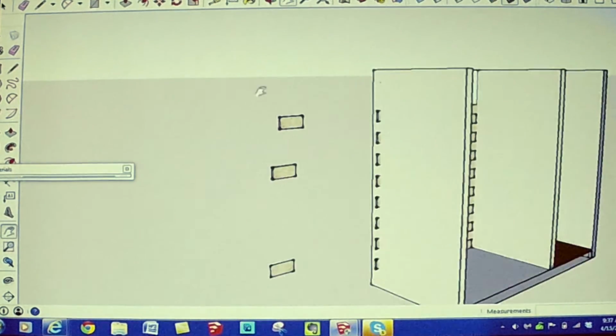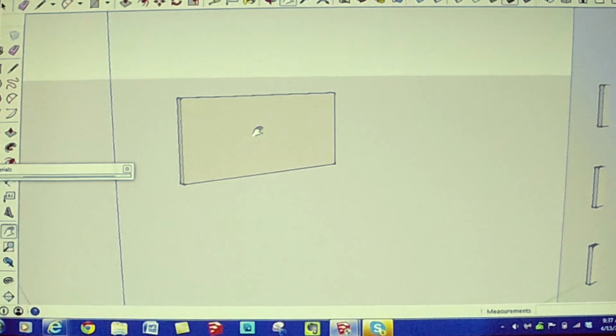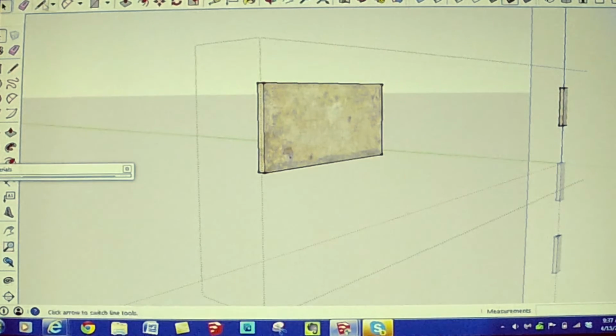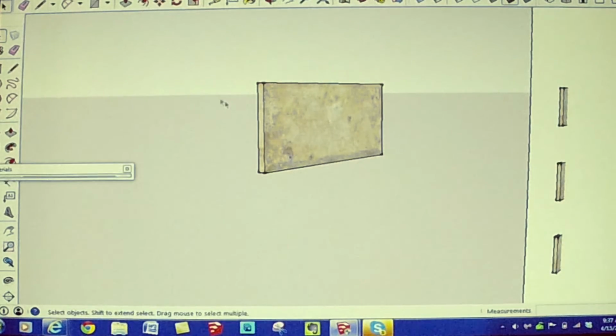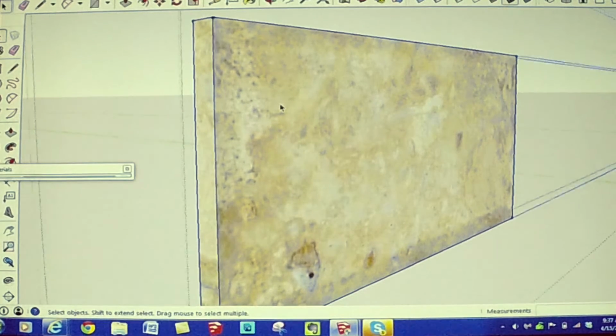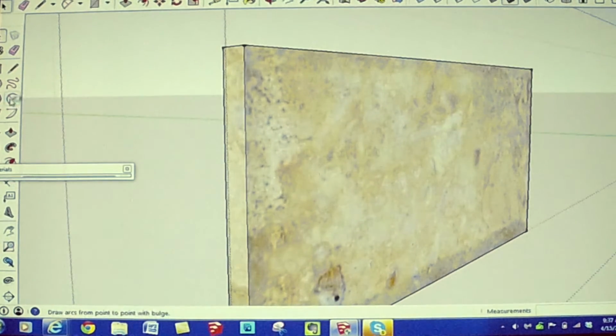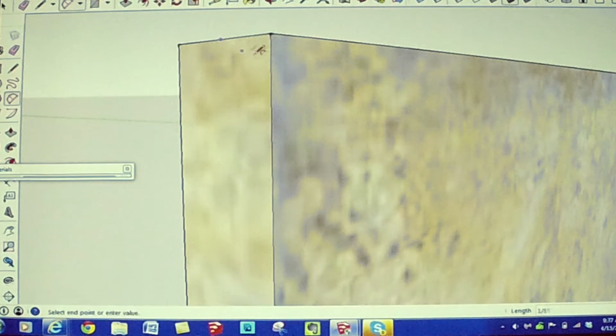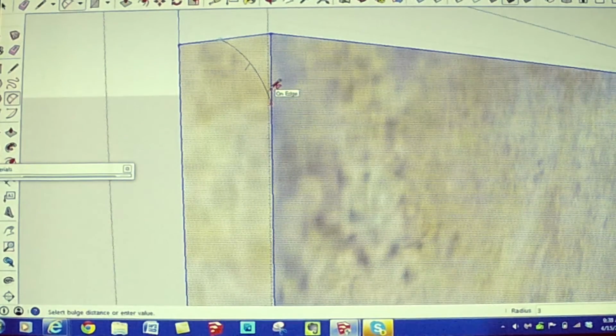So we want to use a different strategy for making our arc. So let's go back to this model. And instead, when I make an arc this time, if I start making it and I say that I want 3 sides to my arc, I'm going to type in 3S, enter. You can see that my arc now has, instead of all those little different edges, just 3 edges.